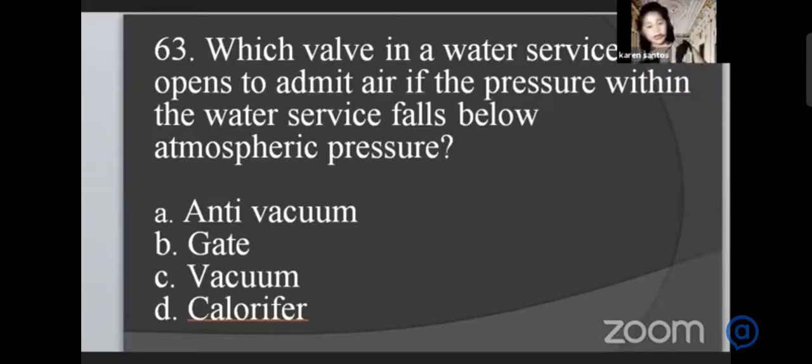A gate valve has to be turned multiple times to go from the open to the closed position. This is to slow the operation and also to prevent water hammer effects. They are designed to be fully open, allowing full flow, or fully closed. Inaalaw siya to fully open para dere-derecho yung pagdaloy, and inaalaw naman siya to fully close para ma-prevent natin yung pag-stop ng flow entirely. Okay?